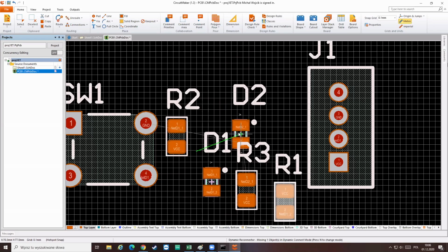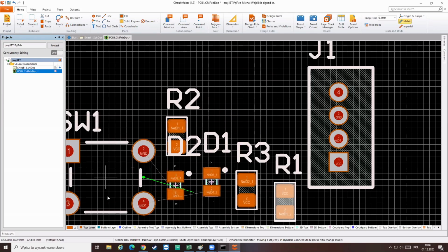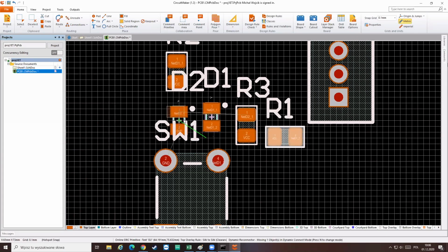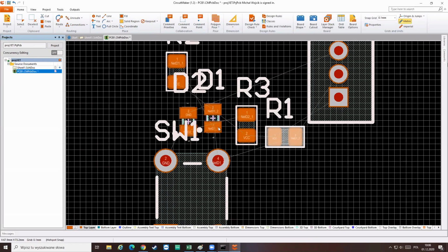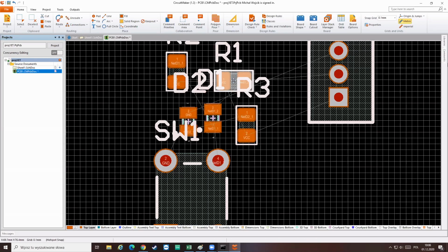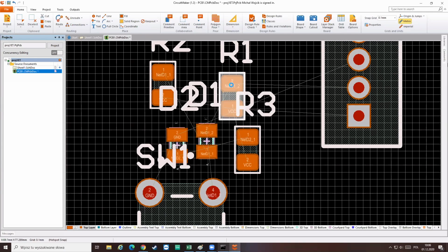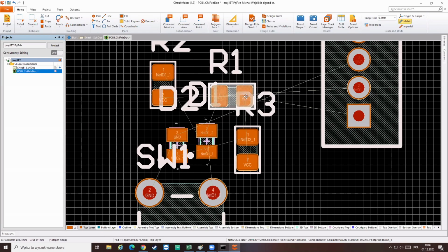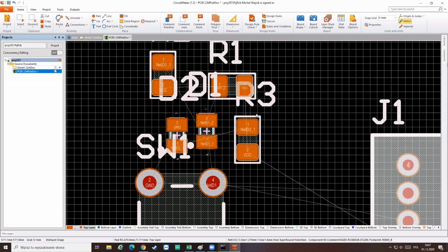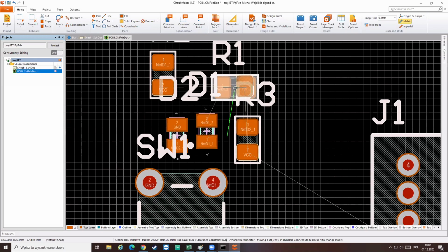I should give you another example. Maybe somewhere will give me the option to do that. Okay, there's no good rotation example. Okay, here will be one. Check out this element R. It wants to have a connection here and here, and just because of the orientation of this element, I'm giving myself a problem, because here I get a clear path, just between those elements, not talking about all the others because I can still move them, right? Just between those elements I have clear, straight paths. If I rotate it, I've already made a crossing just between those two elements, which is not very nice.